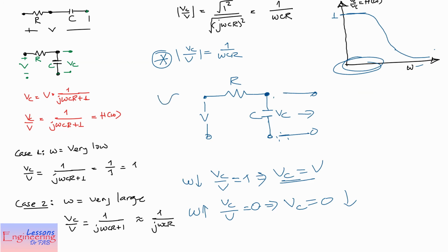Now if you have a low frequency signal, it will pass through while its amplitude remains unchanged. The high frequency signal at the output will be attenuated; as you see, it will be taken to almost 0. Ideally you will not get the high frequency signal, but that's not going to happen. What happens is that you will have that high frequency signal, but it is highly attenuated. Let's say this is the amplitude of the source, but your output amplitude will be very much attenuated and you will not detect it at the output.